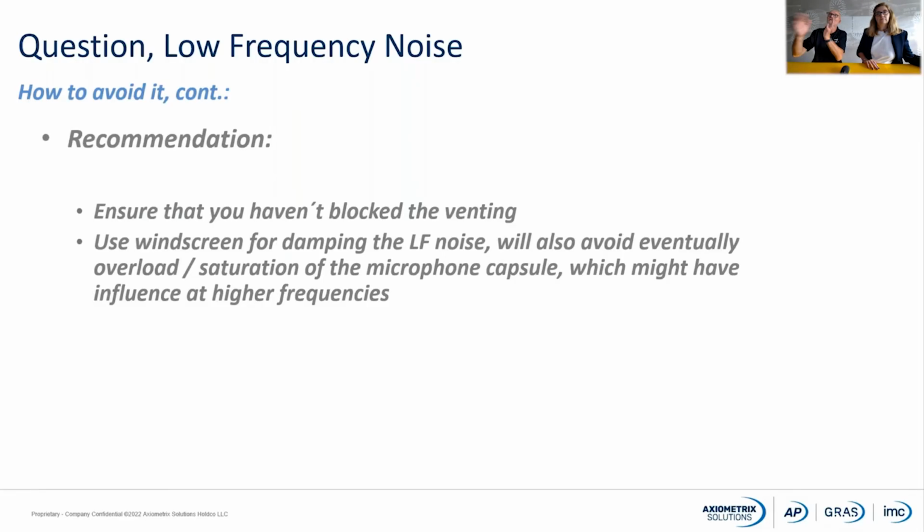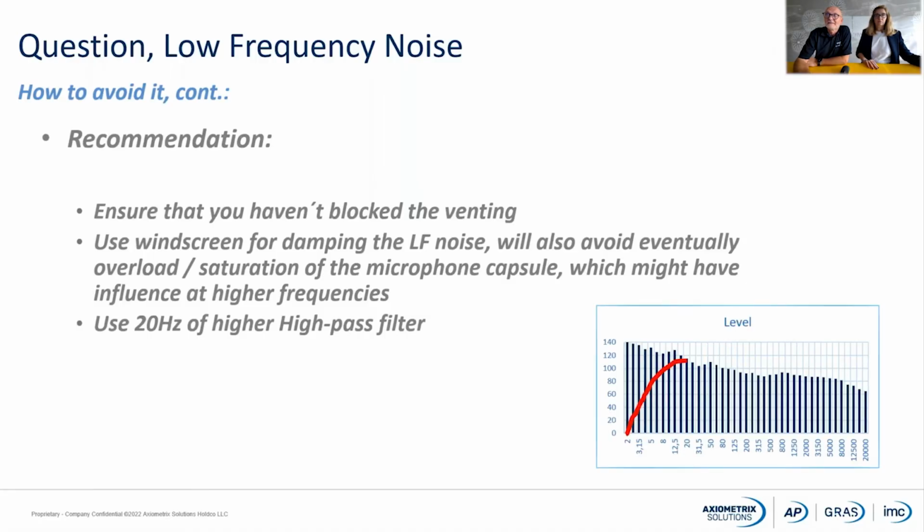So if you try to damp at lower frequencies, then if you overload the microphone at low frequencies, you can't see it, but you might have some resonance tones at higher frequencies, which make your measurements a little bit strange and weird. And use a 20 Hertz high pass filter like this.